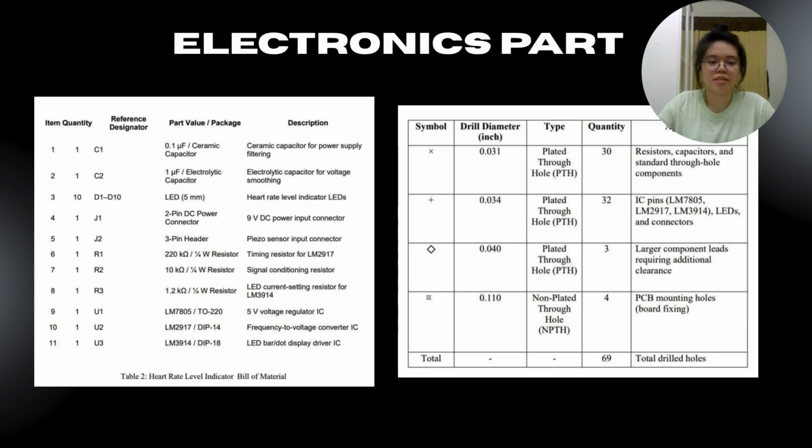Next is the drill table. It shows the drill hole sizes used for PCB fabrication. Our PCB used 4 drill sizes with a total of 69 drill holes for component installation and PCB mounting.